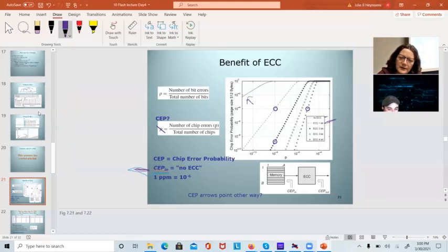then the probability decreases greatly. What's this axis? Chip error probability, oh, page size. So as the page size increases, the probability I get an error also increases. So now, we compare for the same page size here that's like 1%. Oh, it's about the same. I don't get a lot of improvement. But you can see that as I increase the number of error correcting bits, the probability that I'm getting an error gets much, much lower.